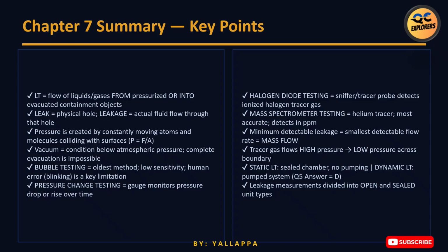Leak testing is concerned with the flow of liquids or gases from a pressurized containment system or into an evacuated containment system. Remember this definition. It appears everywhere. Now let's revisit the most important exam trap. A leak is the physical opening. A crack. A pinhole. A crevice. A fissure. Leakage is the actual movement of fluid through that opening. No fluid movement? Then leakage does not exist. Even if the leak exists.